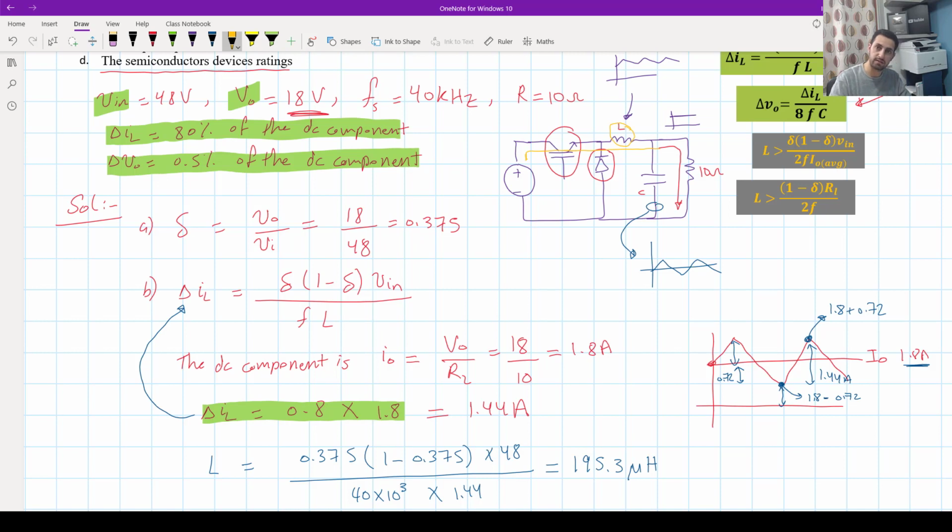In the off time, that current, which is the current of the inductor, will also return through the diode. So both the switch and the diode should handle the maximum inductor current.